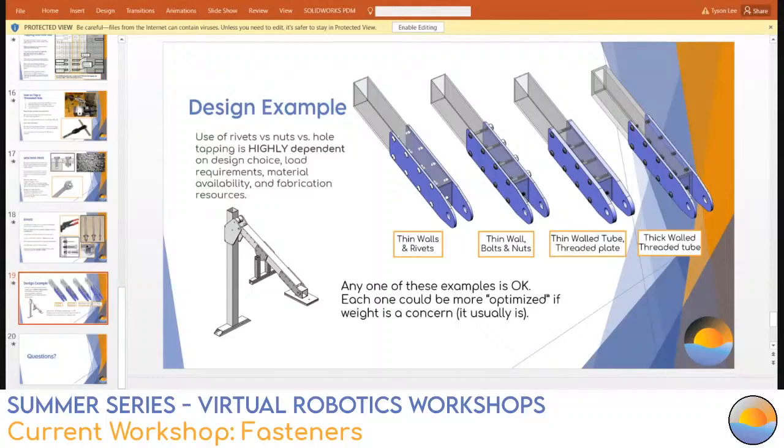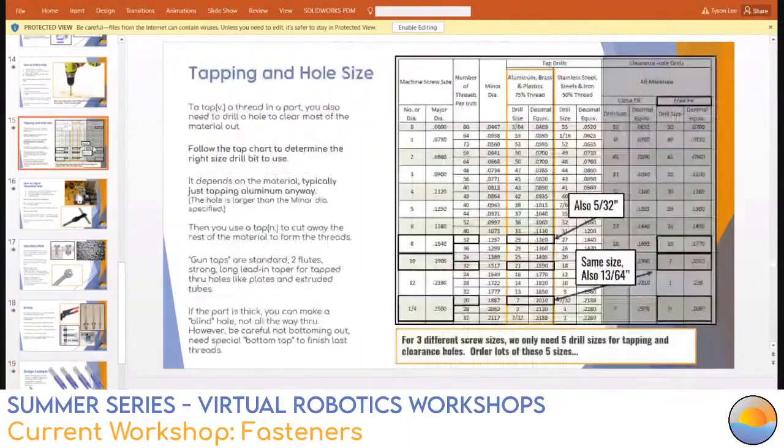Screw sizes are very standardized. So a number 10 is just a 10, and if you wanted to go a smaller size, you can't. There's not an infinite number of screw sizes. They're very standardized in terms of 0, 1, 2, 3, 4, 5, 6, 7, 8, 9, 10, 12, and it stops at 12 because at that point fractional sizes make sense.